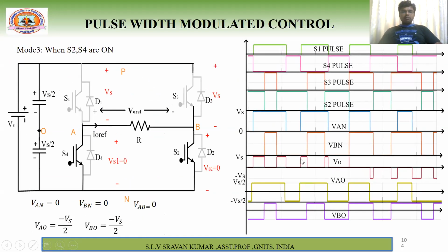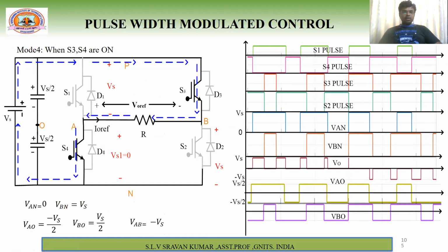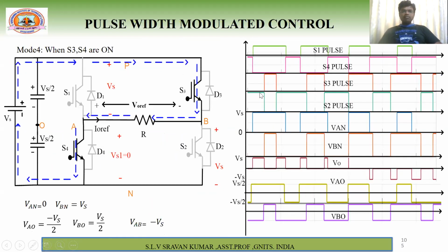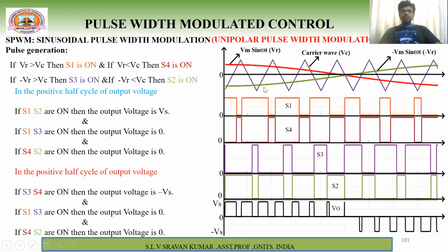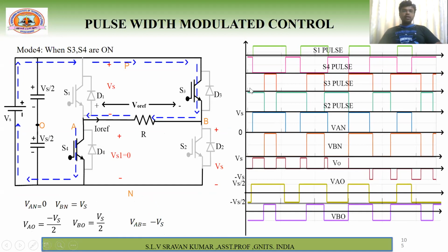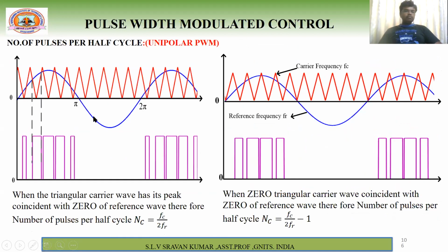So this I have completely discussed about unipolar and bipolar, and this is some other comparison. See, in case of this, the first one: here a triangular wave, you will get up to some time positive, another one some time negative. So here this is one type of PWM, right? Then what happens here? Both are the same, but see here the triangular wave is at zero.